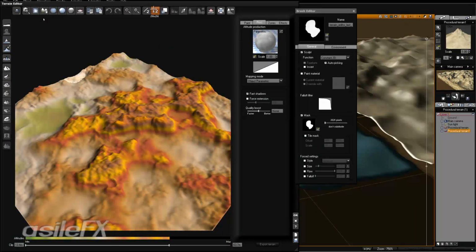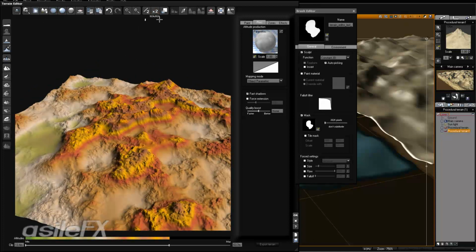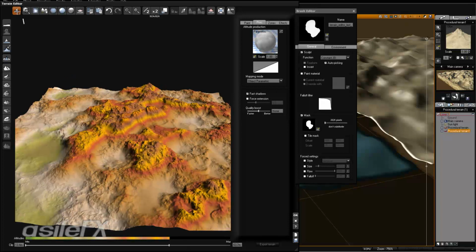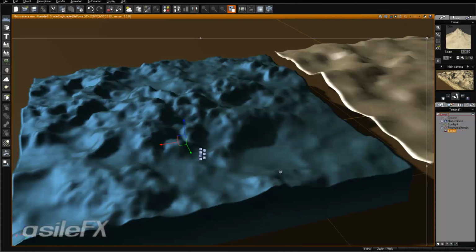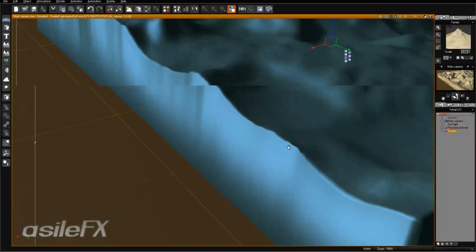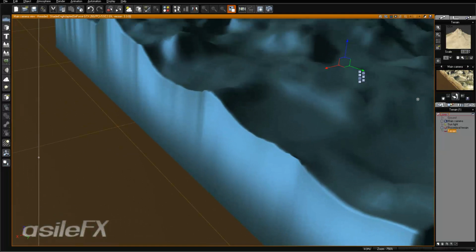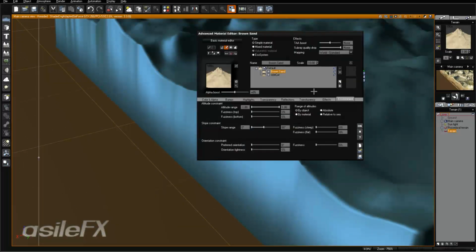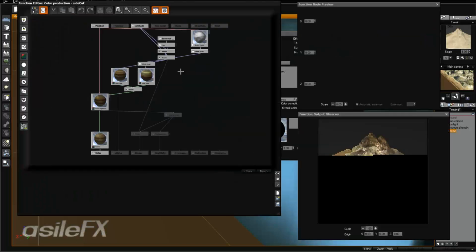So if I edit the object, I'm going to increase the resolution up to 1024 by 1024 by clicking on the ×2 button. And then we're going to switch this over in the upper left to a standard terrain, so it's no longer a procedural. We're going to see a different material showing, and the lines aren't really going to work the same way. It is still connected to the procedural terrain, so it is going to work at this point.